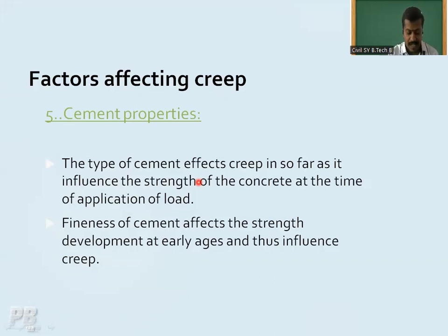Those limits are there. I think I have given it in the laboratory manual. For OPC and PPC, 5 and 10% are the limits for the fineness of cement. Okay, you just check in that lab manual. Maybe I have taken it from my university. Okay, you just check it. But those limits are there.